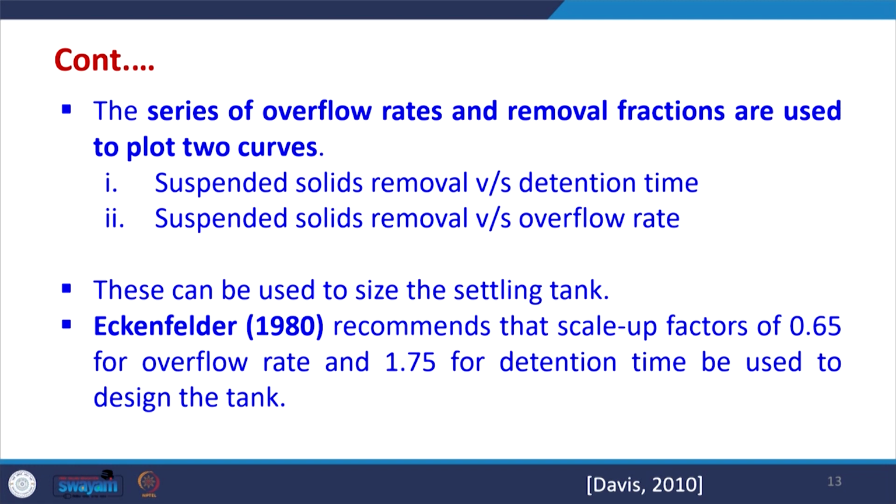And from these, Eckenfelder has suggested to scale up, taking 0.65 for the overflow rate. Similarly, for detention time we can take a little higher value, like 1.75 of whatever we get, and from that we can design the system as earlier.